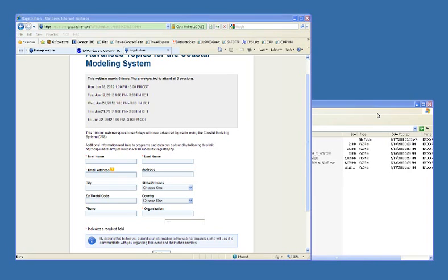Another question from Patrick. He says, can we know the projection if you don't know the information? That's really tricky. Sometimes if it's geographic coordinates, you can tell that they're degrees, and so you have an idea of where that is. Otherwise, you're really on your own. If you're working in a project and somebody gives you some files, you hope that they are in at least a local UTM zone or a local state plane zone, so you have a general idea of where it's located.